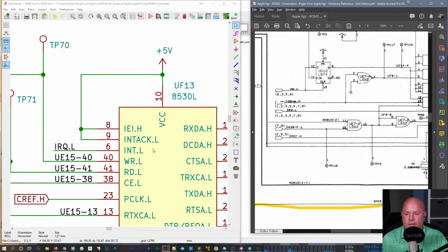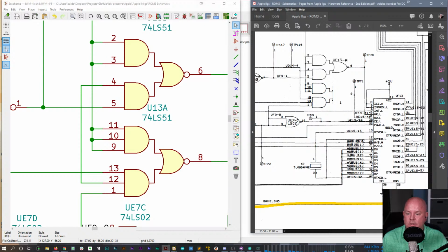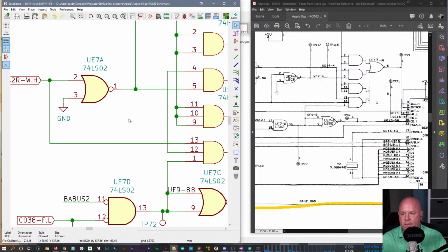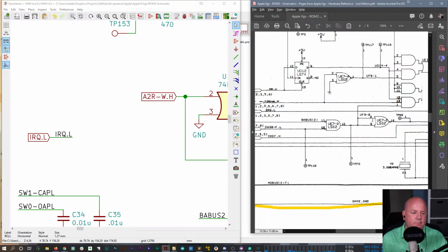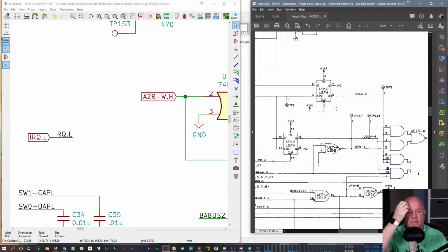And then we're up to the ready. So the other way I wanted to double check this is if we look at this gate array. So that one's connected to these two, 13's over there, 12 connects up to 4, and then it goes out to something else. And I think that something else is that flip-flop. Okay. And then all these other signals are connected to something that goes up. 6 and 8 are taken care of. Okay. So what I want to do now is we've got unit A is done. So now we need to add the flip-flop. So let's see if this standard flip-flop is going to work for us, or are we going to have to get creative? Because I think this is a 2 unit. So this is UD12 LS74.